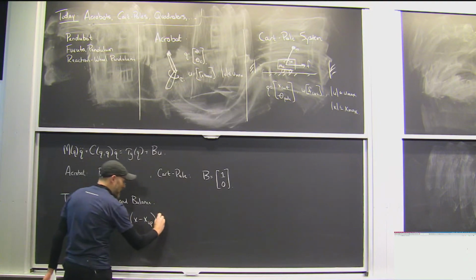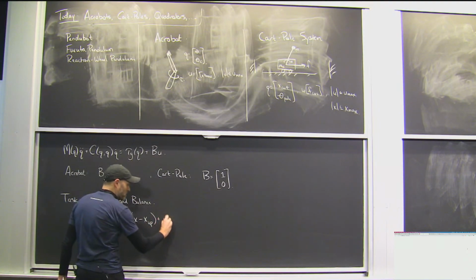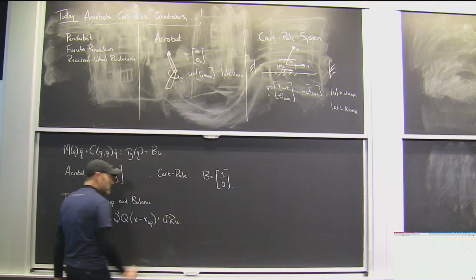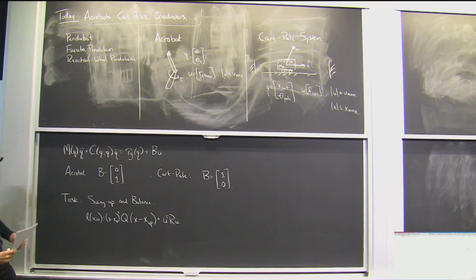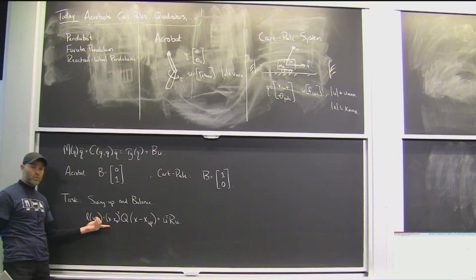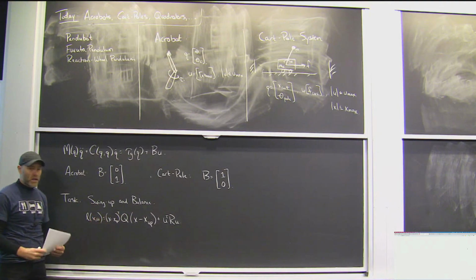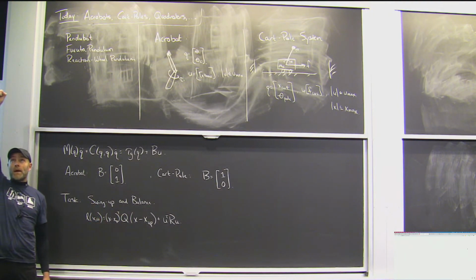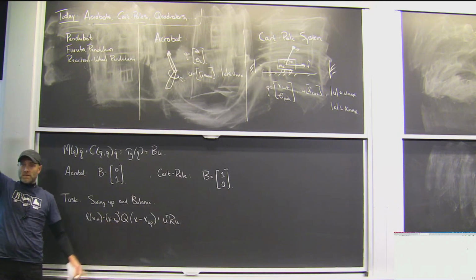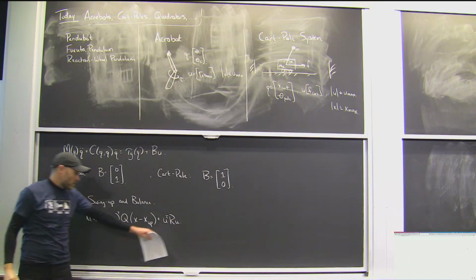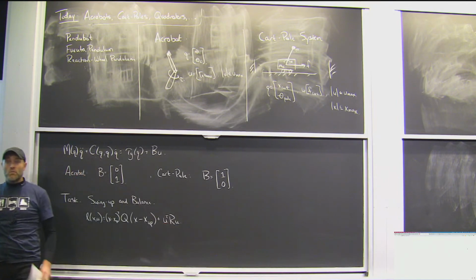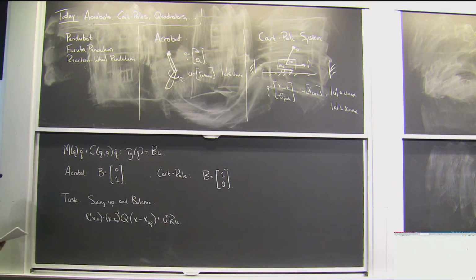And then for my actuator cost, I'm happy again to do something like this. Okay, that's a perfectly reasonable way to write a cost function, saying I'm at 0 cost up here if I'm at the top and I'm applying 0 torque. And the farther I am away, quadratically, I'll penalize myself in state, right? And similarly, I want small actions, so I'll make R positive.